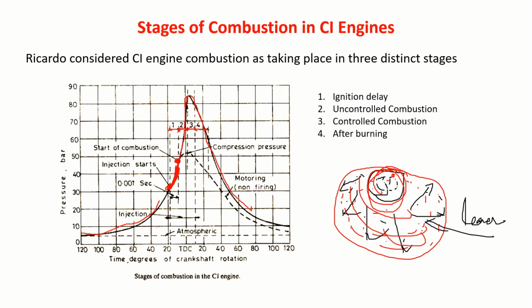During this stage, too much fuel has accumulated, and it may simply set up a pressure wave. That is what we call diesel knock. Because of that, the engine will start running rough.